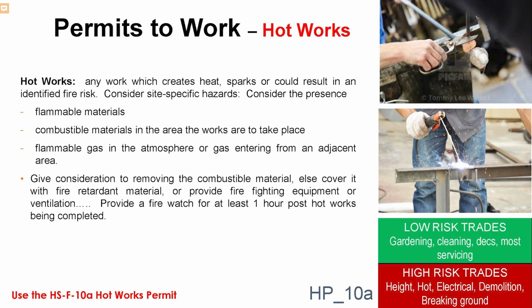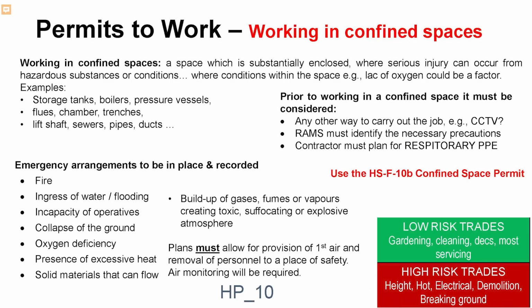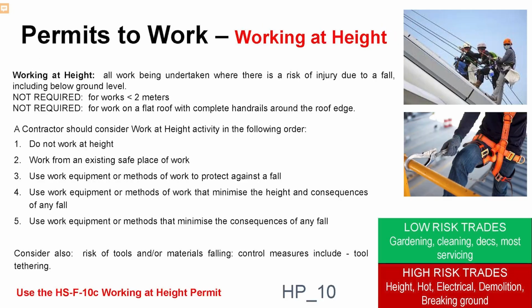So it's just about how you think about these risks, maybe ventilation, firefighting equipment. And working at height, obviously, working in confined spaces. So that's obviously about risks of lack of oxygen, where spillage would cause harm because you can't get out or something like that. So you need to think about the emergency procedures for how you would get out, and maybe the example it gives on there as well is about CCTV for monitoring to make sure you're safe. And obviously also PPE.